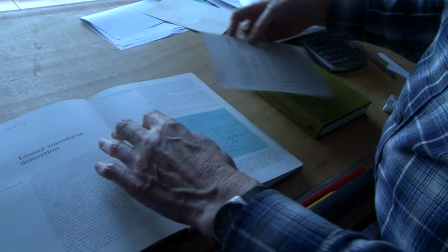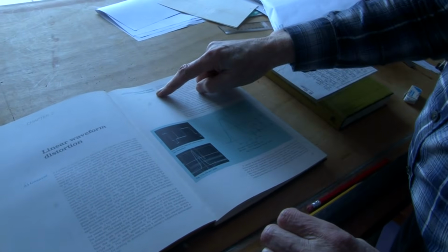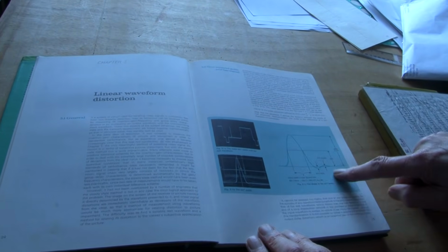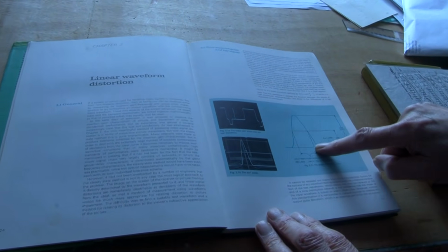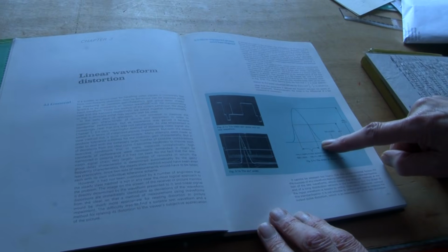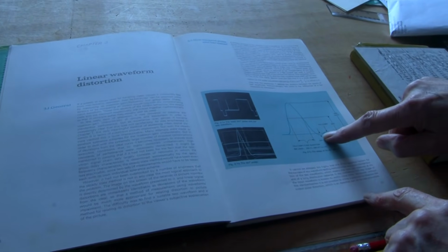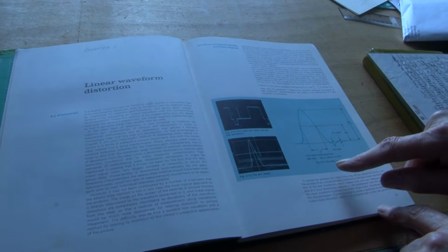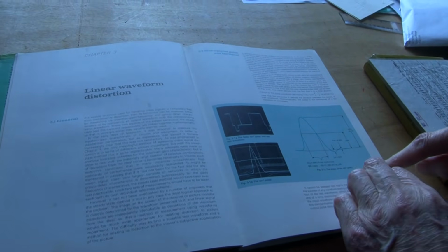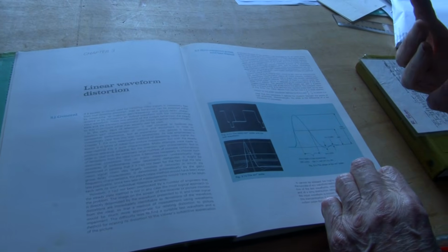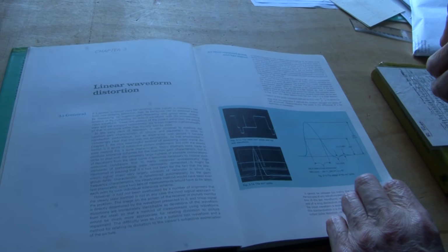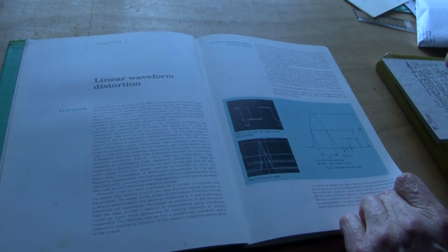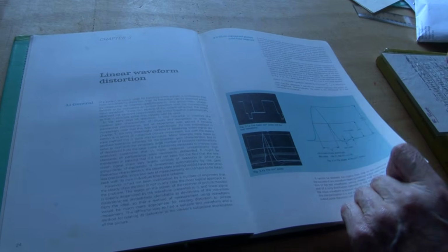And inside we can see here the sine squared pulse and bar signal, and the description relating to it, the T pulse, with, as we had, a bit of a wriggle on the end. And the T pulse, incidentally, had typically a 1T pulse or 2T pulse, the 1T being for 10 meg bandwidth and the 2T being for 5 megs bandwidth.